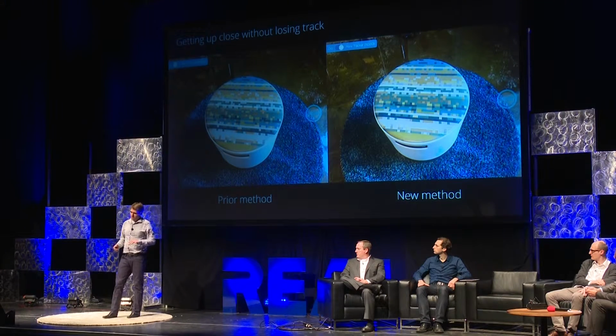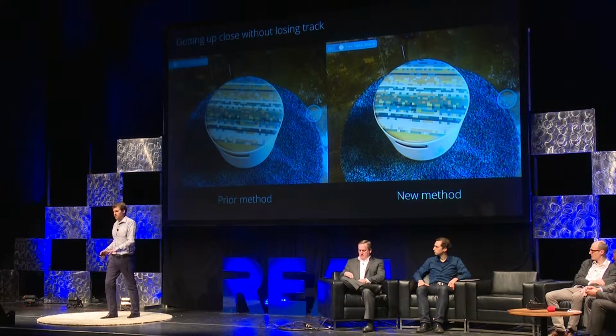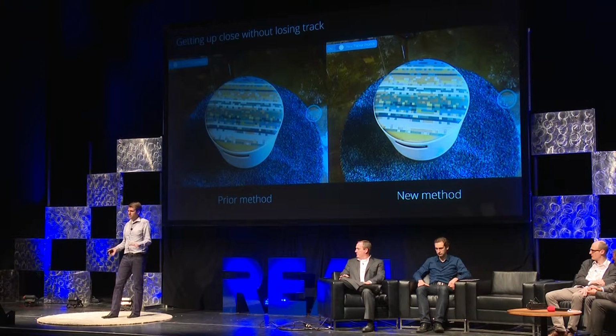Another thing that happens with consumer depth sensors like the Kinect is that if you get too close, the depth sensing fails. This is for a variety of technical reasons, but users don't understand that. I mean, they're used to cameras getting better, so they try to get as close to things as they possibly can to get more detail. That turns out to cause these systems to fail, and users don't understand why.